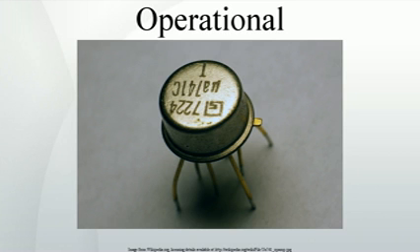Open loop. The magnitude of AOL is typically very large, 100,000 or more for integrated circuit op-amps, and therefore even a quite small difference between V+ and V- drives the amplifier output nearly to the supply voltage. Situations in which the output voltage is equal to or greater than the supply voltage are referred to as saturation of the amplifier. The magnitude of AOL is not well controlled by the manufacturing process, and so it is impractical to use an operational amplifier as a standalone differential amplifier.